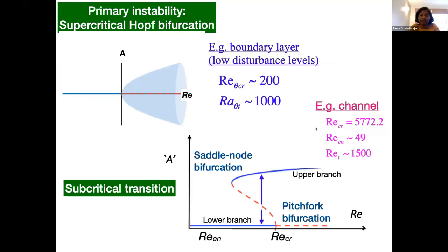number taking place. There is another Reynolds number called the energy critical Reynolds number, below which you can show that all perturbations decay. Every perturbation will decay, and that Reynolds number is very low, it's just 49. So it's irrelevant to most of the things we're talking about now. But theoretically, nothing can ever grow below 49. Now, at in-between Reynolds numbers, particular kinds of instabilities can show up.